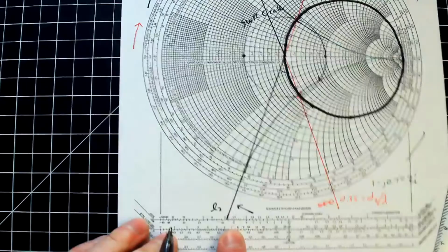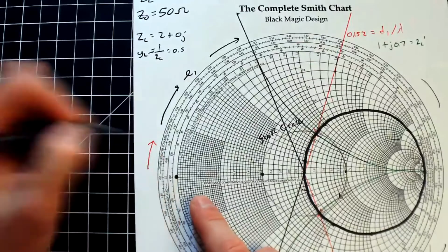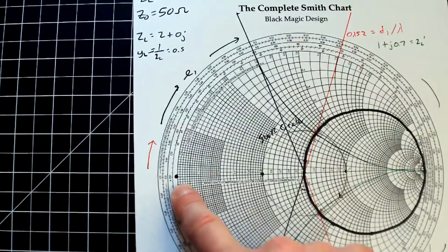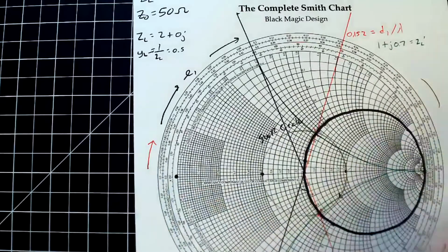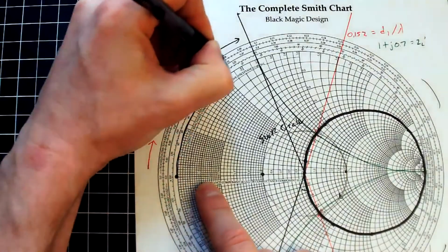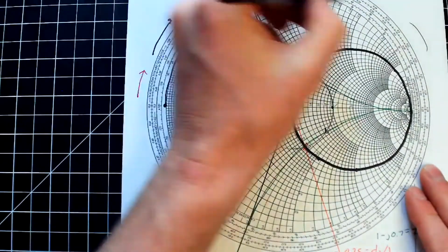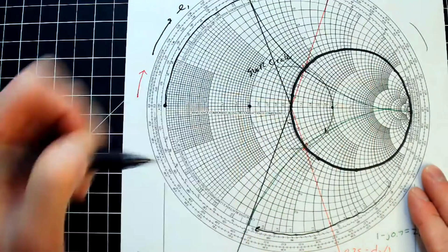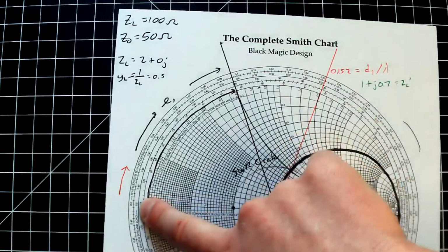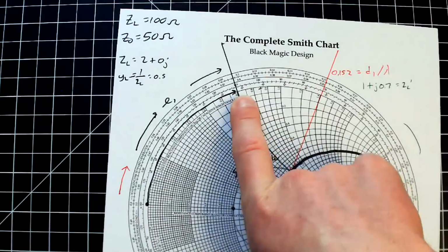All right. So the idea is actually, if you want to interpret it intuitively, you can imagine that you're basically starting here. You imagine I'm looking down an open circuit line, which is now being flip-flopped on the left, and I'm asking how far do I have to go along this before I hit that exact value there. And then they negate each other when I put them in parallel. And then of course there's another one that's going to go all the way around this way. So you're going to read off. Notice you now have to read this on wavelengths towards load for this particular case, because things are backwards in this case.